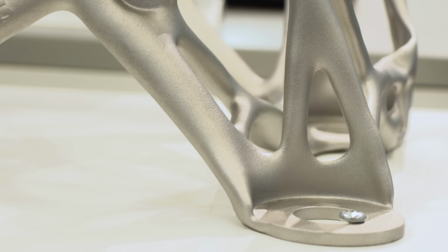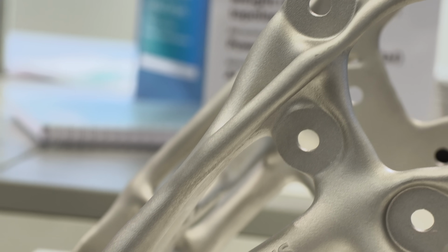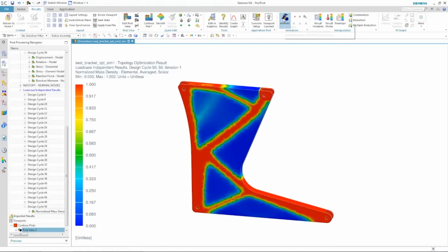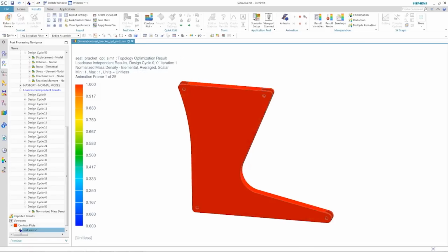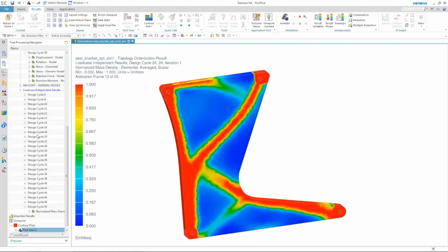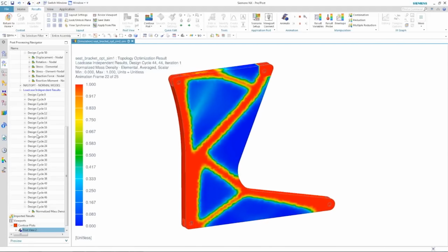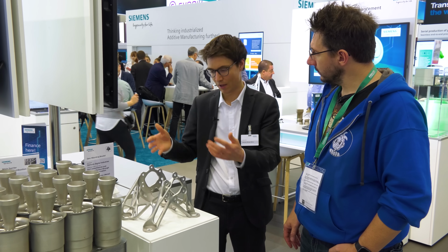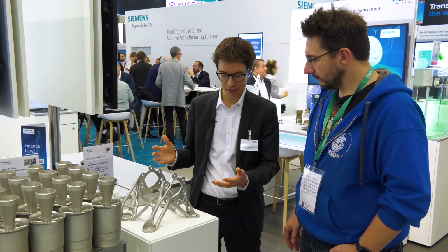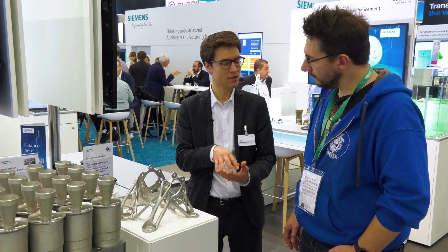But it's pretty amazing because on this part we also show our customers the build process simulation, because our customers want to make sure, again, that what they send to the machine is printed correctly. And there's a lot of thermal influence in the metal printing process, you're aware of it. So we have to make sure that we can account for this and correct the geometry of the part beforehand if needed. And that correction happens digitally. It happens digitally. It happens in the software SIMCENTER 3D AM. We can simulate the interaction of the laser in the machine, or in this case of many lasers, 4 lasers, in the machine with the material in the machine, with the powder, and see the thermal influence and the results, the deformation.